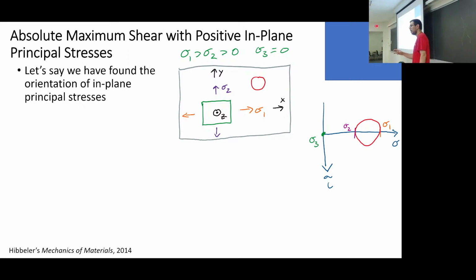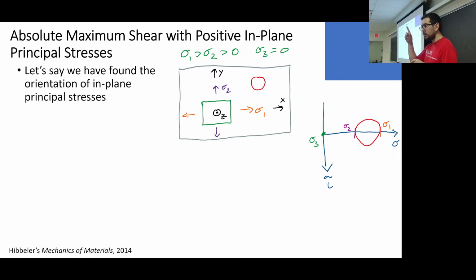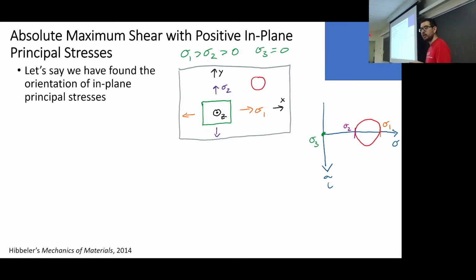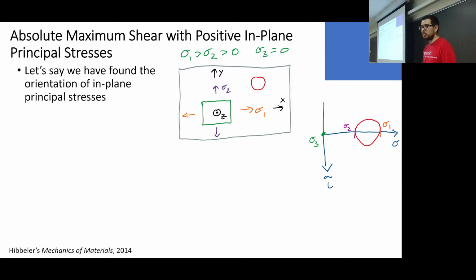Mohr's circle. Just as a review, what is the maximum in-plane shear stress there? Yeah, Dylan. Sigma 1 minus sigma 2 over 2. Right. The diameter is sigma 1 minus sigma 2. The radius of that circle is going to be half of that, and so top or bottom is what you just said, the quantity sigma 1 minus sigma 2 divided by 2.